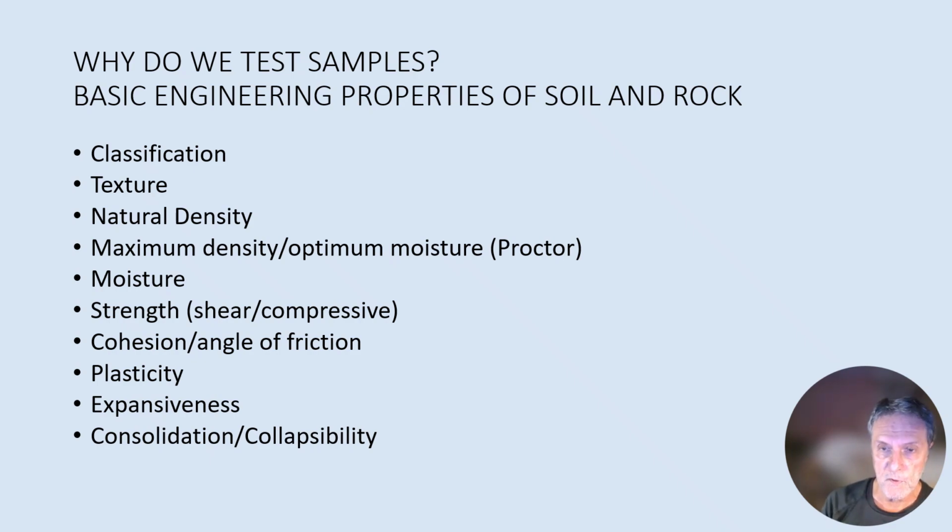Some soils, for example, in East County area of San Diego, are very porous and dry in their natural state. If they're subject to additional water from irrigation or swimming pool leaks or what have you, sources of moisture, they can actually collapse. And we can measure the degree of collapse or consolidation in the lab.